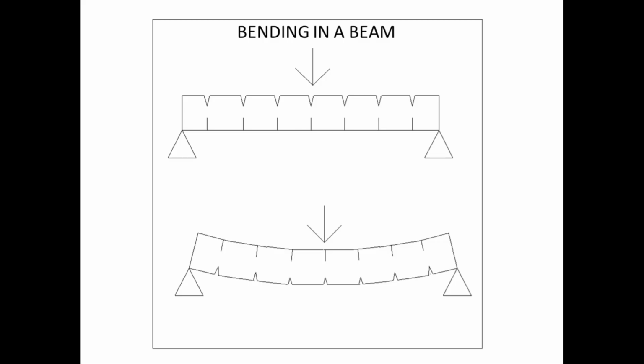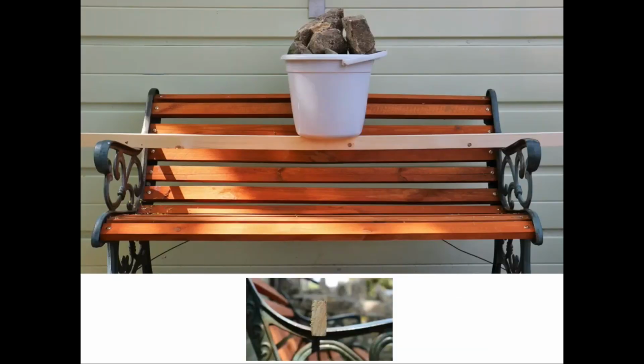One of the principles that's happening here is that the span, if you like, if you consider that beam as a simple bridge, the span of it is related to the depth of the beam. So it's called the span to depth ratio. And every time you're designing a floor or a bridge of any kind or a platform that has to span from one side to another, you will get a simple rule of thumb to calculate how deep that beam has to be in terms of the distance of the span.